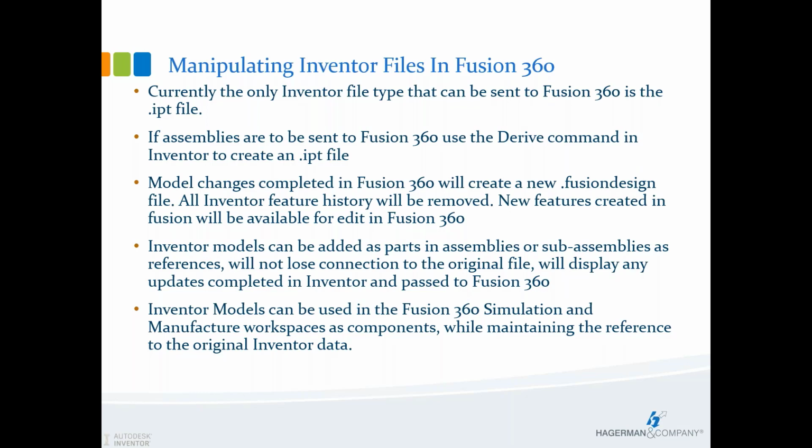Any model changes that we do in Fusion, if we make any edits to those Inventor files, a new Fusion design file is created. The original Inventor file is not affected by those changes. If we want to maintain any of the connection or the reference to the Inventor files, we would use those as components inside of Fusion Design assemblies, and we'll see how all that looks here in just a little bit.